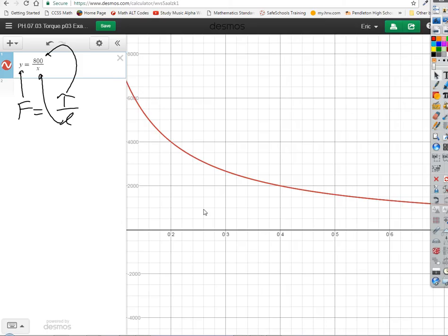Now, what's the obvious disadvantage? If you put really small tires in, you're not going to be able to go nearly as fast, but you get the idea. The smaller the tires, the more you're going to be able to use the torque in your engine. Now, what's the other thing you could do, though? Change ratios. You could change the gear ratios too, couldn't you? You could change the gear ratios so that you could effectively change the amount of torque that the engine's providing to the axle, right?